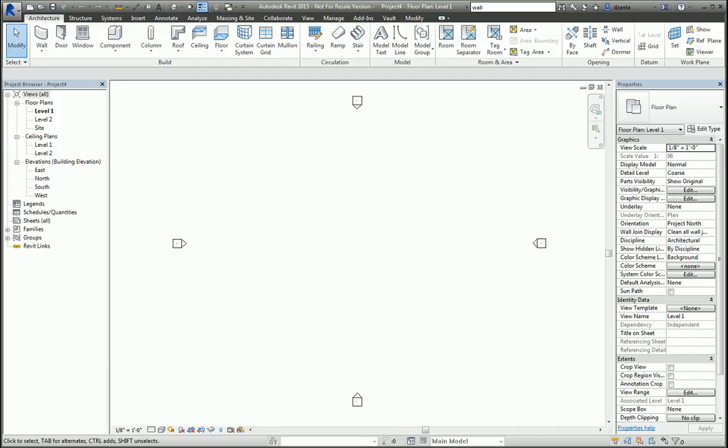In today's screencast, we'll be looking at the wall command in Revit. Here I am in Revit in a default architectural project. In the Architecture tab of the ribbon in the Build panel, we have the wall command. If you hit the little black arrow next to wall, you'll see that there's a sub-panel that opens up, and it gives me access to either architectural walls, structural walls, or wall by face. And once the walls are created, we have access to the sweep and the review.